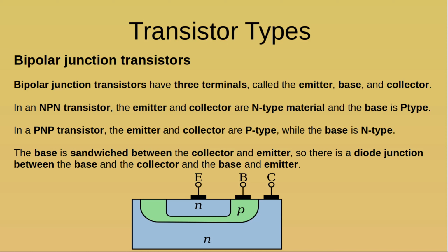Which of the following indicates a silicon NPN junction transistor is biased on? 0.6 to 0.7 volts. And it'll vary by transistor. Maybe even within a particular type, like a 2N2222, if you actually measure them, they're probably slightly different for each one.